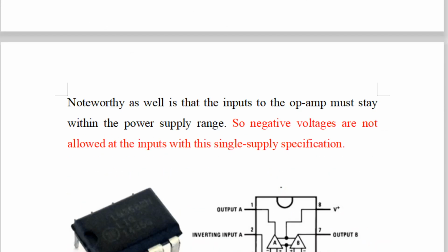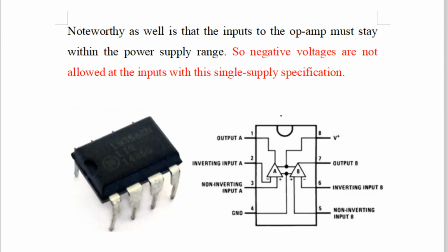So this is the LM324. One more IC is available in the market for op-amps. There are two operational amplifiers present in one IC only. So here one and here one. One op-amp will require 2 inputs, 1 output, 3 terminals. Another will be 3, total 6, and 2 terminals for power supply. So here you can say plus VCC and ground. So this works on a single power supply only.